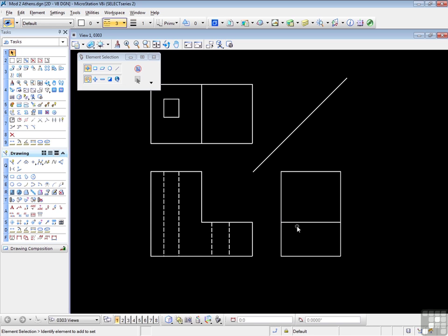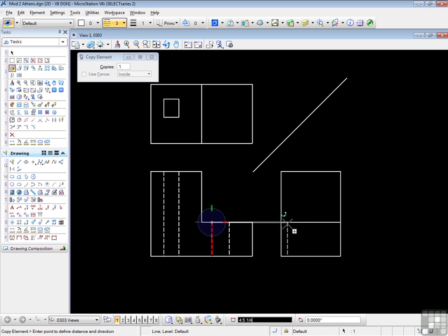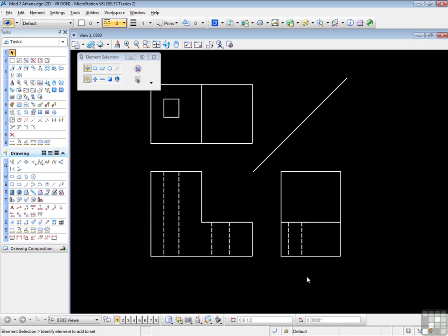And I'm going to put the same hidden lines for that over here. I'm not going to bother to put these hidden lines for this object on the right side of view at this point. You can do that later yourself. I'm interested in this, which is in this area here. I'm going to actually do this, go back to that's on, do a copy, do from here and across to there and across to there. So there's the extent of that rectangular hole as seen from the front and the right side view.